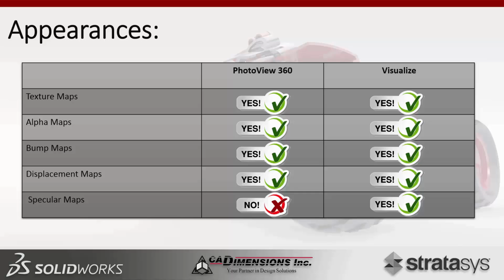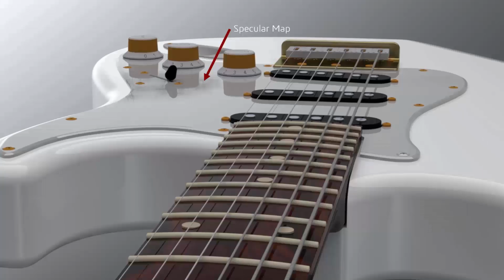Now, a specular map basically allows you to control the specular amount that you're getting in the appearance, up or down, with a black and white map. This would be used in scenarios where you're trying to create something that may look worn or scratched, something where you're trying to get the highlights to pull out of it. It's not reflectivity, but it's pulling the specular amount down.